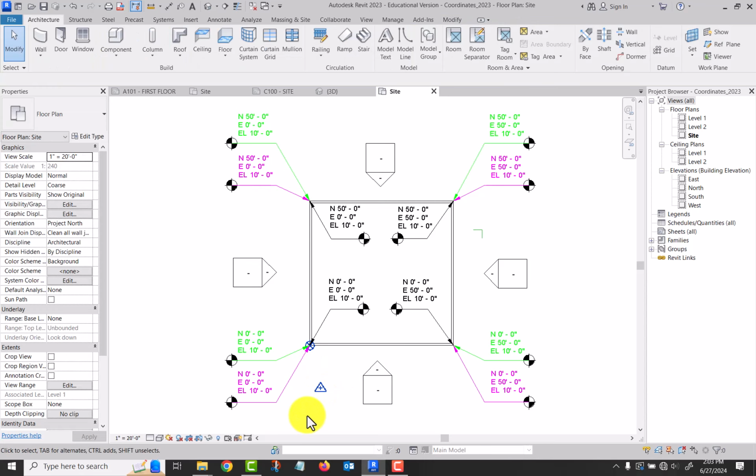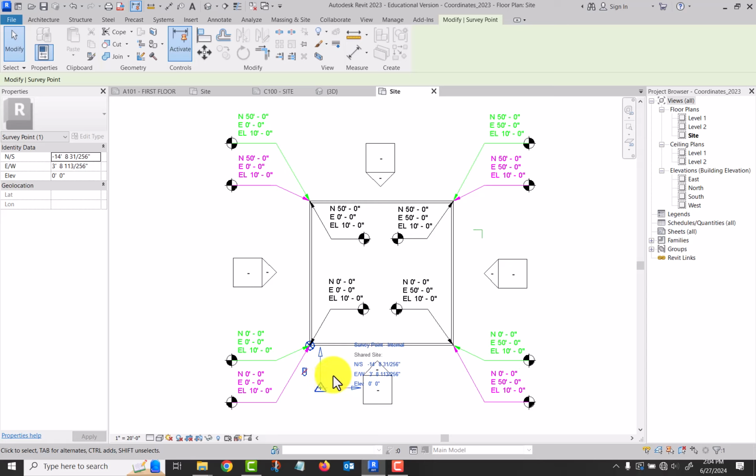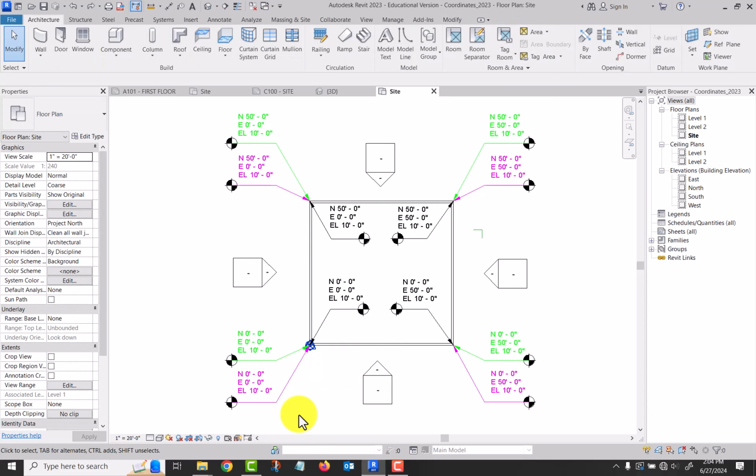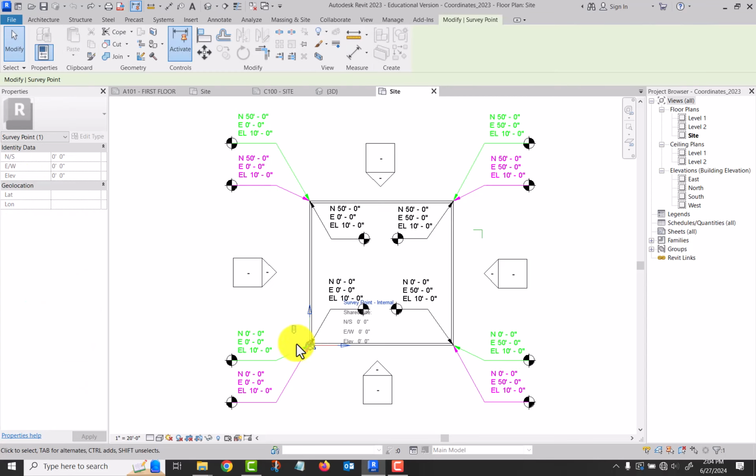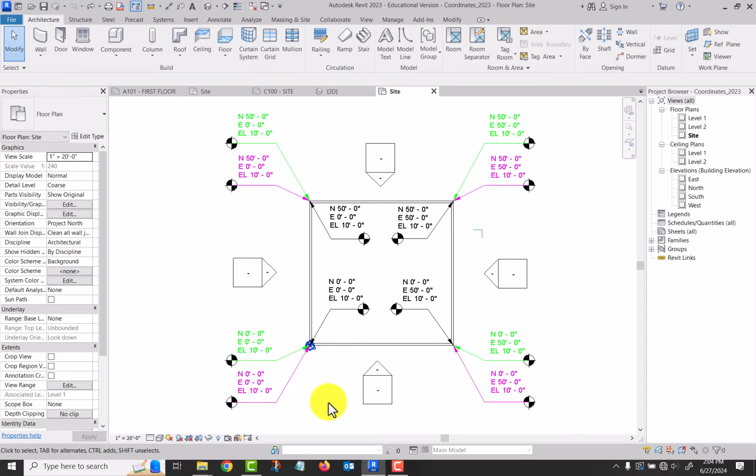And you notice the coordinate system did not change, but the marker moved, and it's got a move value here, but the coordinate system didn't change. So I'm going to Control Z and go back. And let's make sure that that is clipped. Okay, it is clipped. Now, you can move your building without moving the base point. You get into some weird kind of things sometimes.